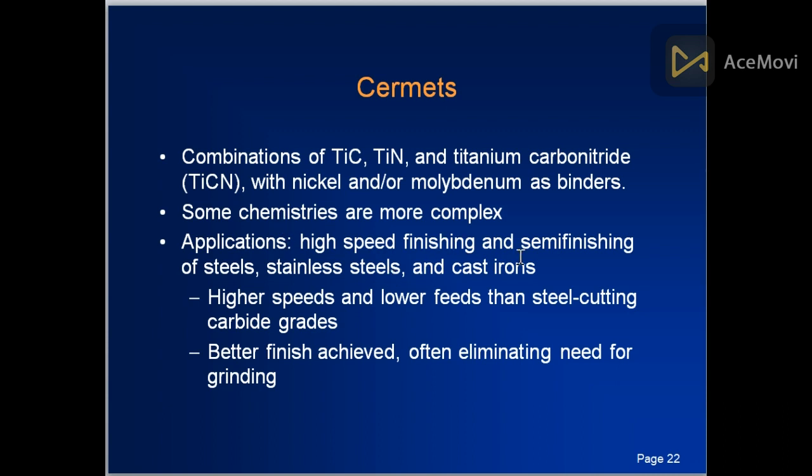Application: high speed finishing and semi-finishing of steels, stainless steels, and cast irons. Higher speeds and lower feeds than cutting carbides create a better finish, often eliminating the need for grinding.